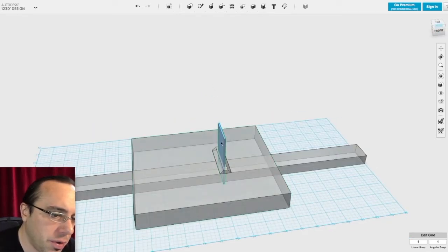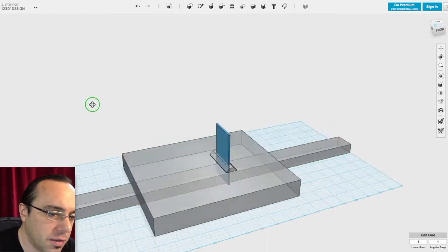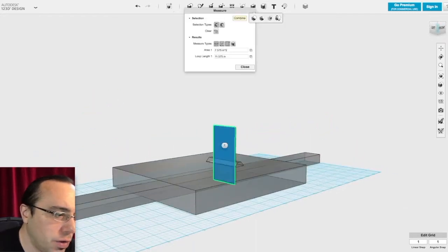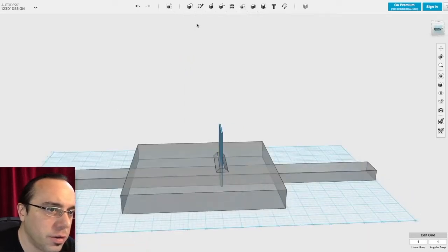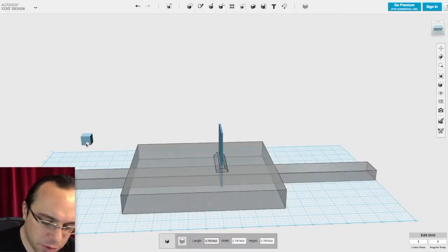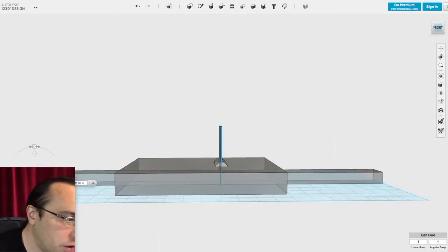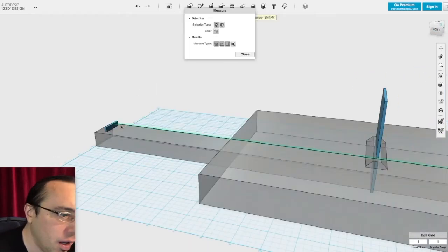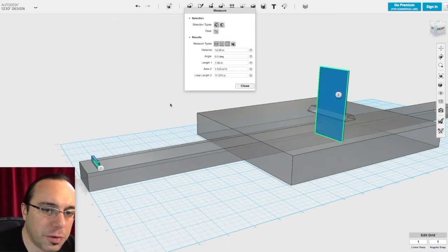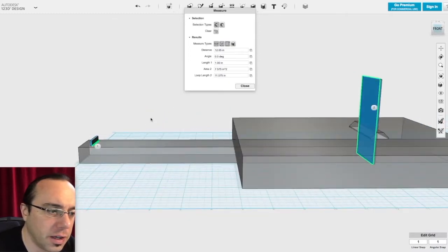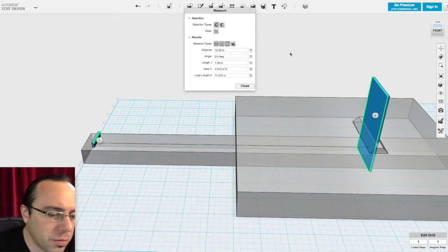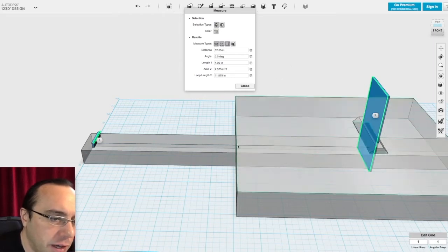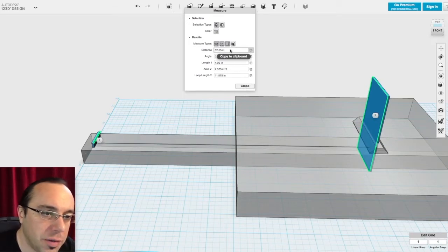This right here is just going to be marking the bridge for measurement against the end right here. And we want the distance between where our 0 fret or our nut or whatever it is going to be. I'm going to do that, and this will be our 0. Don't want it at the end, so maybe minus 11.5. Stick it right there. And the distance between our 0 fret and our bridge is going to be our scale length, which, as he said before, was going to be about 14.75, so either 14 or 15. It really doesn't have to be exact because we're going to be laying out our frets anyway. So we can pretty much choose whatever we want. So let's say we want that to be 14 inches.